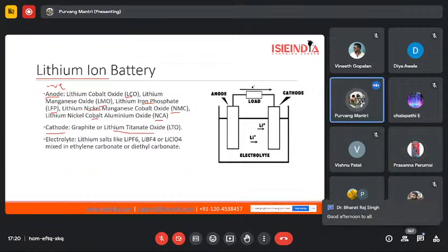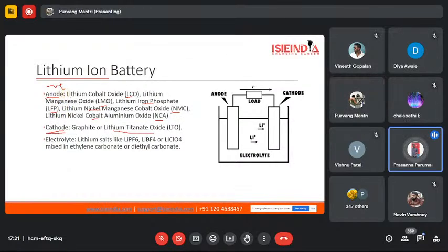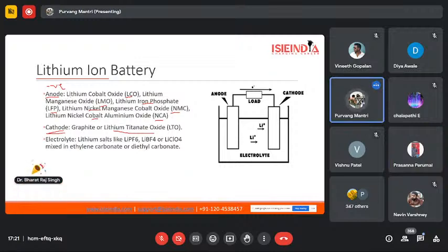If you search, there are two types of battery electrolysis chemistry. When we are using the battery as an electric source, the anode would be the negative terminal and the cathode would be the positive terminal. But when it comes to charging the battery pack, we are actually intercalating the lithium ions in the negative electrode, in the graphite. So at that time the cathode would be the negative electrode and the anode would be considered the positive electrode. Okay.